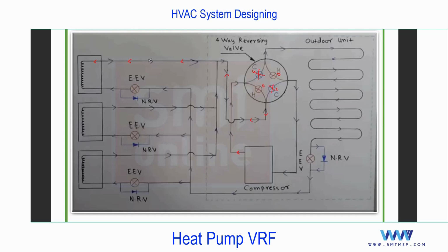In general, this unit we can call a heat exchanger. We are not giving the name evaporator or condenser because the cycle can reverse. In cooling only we can say indoor evaporator, outdoor condenser, but in heat recovery or heat pump, we can call this a heat exchanger because this will change. So now this will become the condenser.